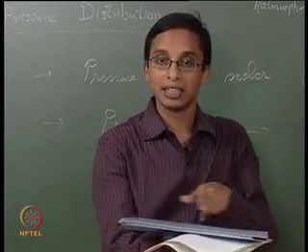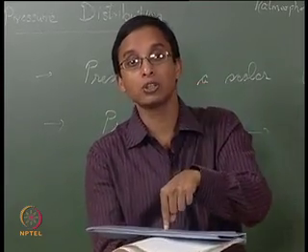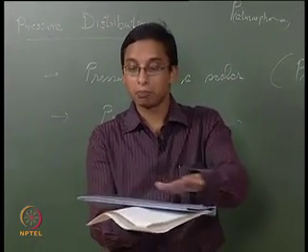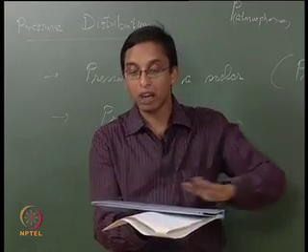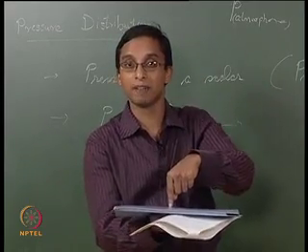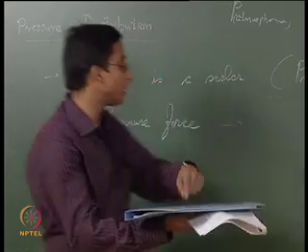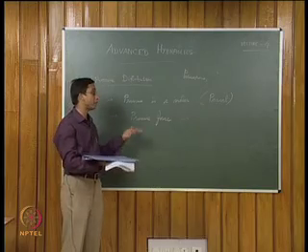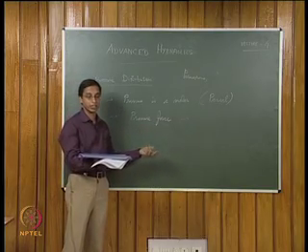Please note that forces will act normal to the surface. The pressure times the area of this surface will give you the force acting normally to this surface. So, pressure will exert a force normal to whichever plane we are considering.